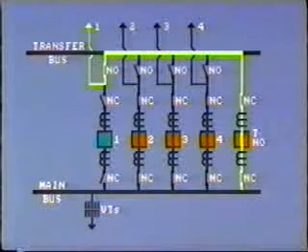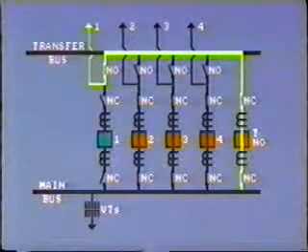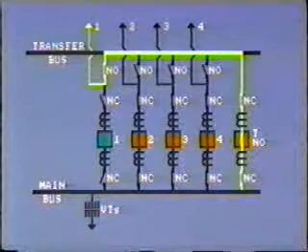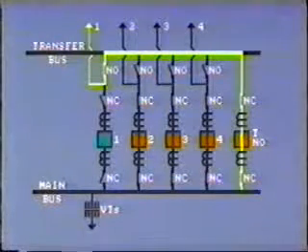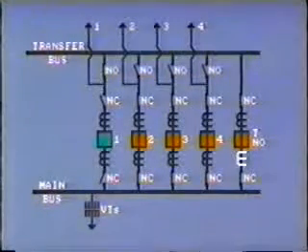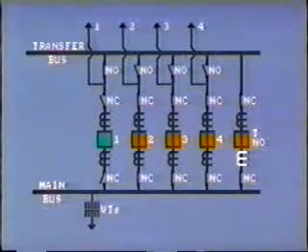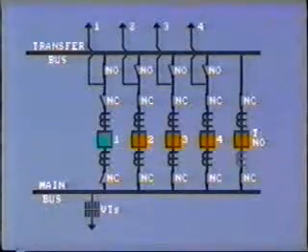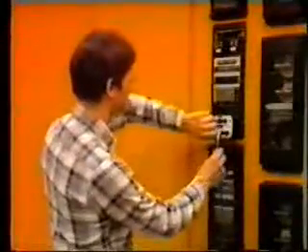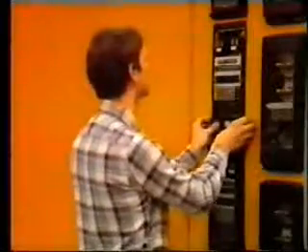While in this configuration, the transfer bus acts as part of the line and is thus protected by the line protection. The inboard CT of the bus tie breaker becomes part of the line protection. This could pose a problem where different protection settings are required for different transmission lines. There is always the possibility of forgetting to make the change or perhaps making incorrect settings.